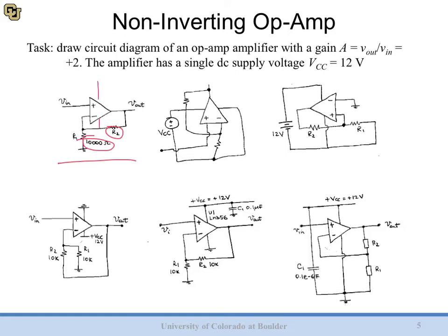Additionally, we haven't labeled the voltage rails on our op-amp, which makes it a little bit confusing. Nowhere on this circuit does it say we're using 12 volts. So for those reasons, we don't like this first one. The second attempt is obviously misleading. You can see we haven't labeled input, we haven't labeled output. Additionally, if we follow the data flow, we're going from left to top, which is very weird and non-standard.